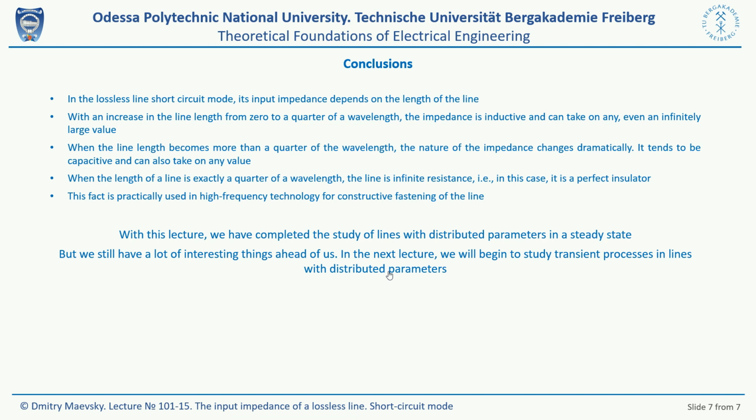In it we learned some interesting and unexpected things about the behavior of a lossless line when its output terminals are shorted. In particular, we learned that in the lossless line short-circuit mode, its input impedance depends on the length of the line.